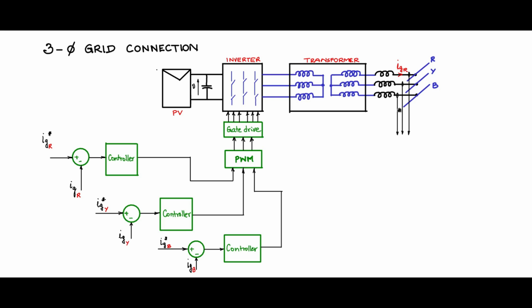Now coming to the reference setting through the MPP algorithm, let us say the voltage across the PV terminals is Vt and the current through the PV is measured with another Hall sensor, and is called It.